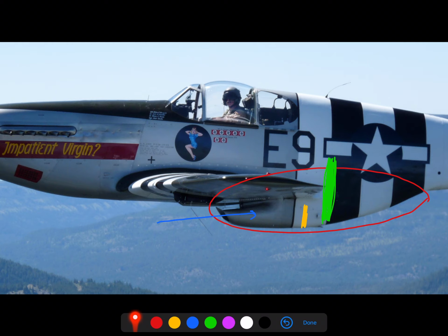Again, this is all done by contact, so depending on the amount of air that we allow to flow through this housing, combined with the amount of oil that we're forcing to flow through the oil cooler, we can regulate the temperature of the oil fairly accurately. Similarly, the radiator has its own door at the trailing edge here, and that will regulate airflow through the radiator. And in the very same fashion, we can regulate how much cooling we're receiving through those two fixtures.